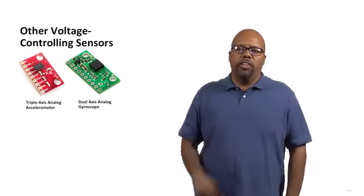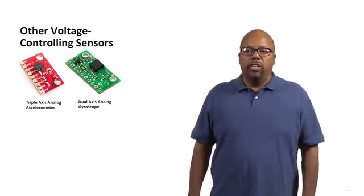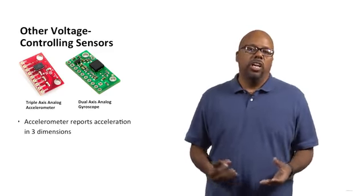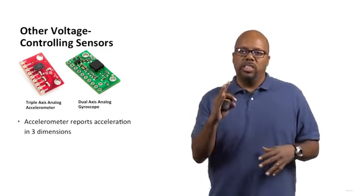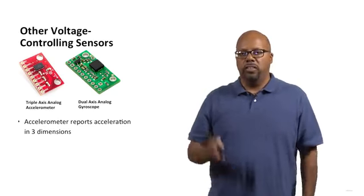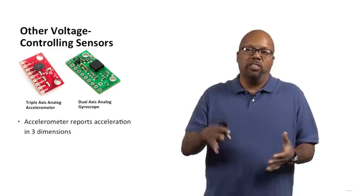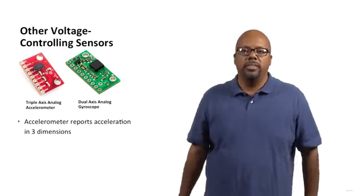The first one, the one over there on the left, is the triple axis analog accelerometer. So an accelerometer basically senses acceleration in 3 dimensions, so x, y, z. It'll tell you the acceleration. So this is useful for telling your orientation, right? Because there's always the acceleration of gravity. So you can tell the orientation of your device based on what this thing reports back, since you know what the gravitational acceleration is supposed to be.